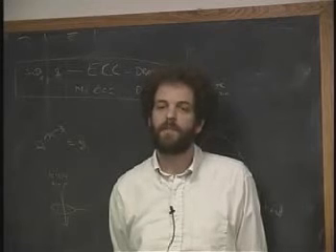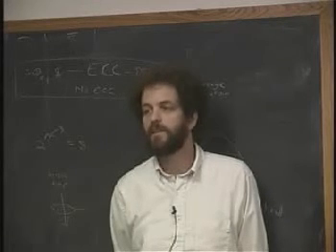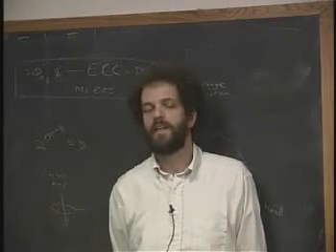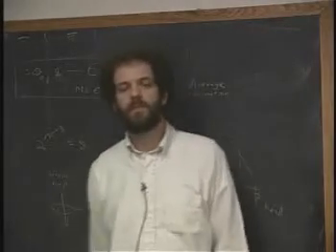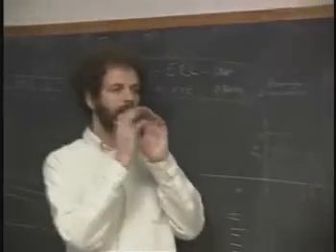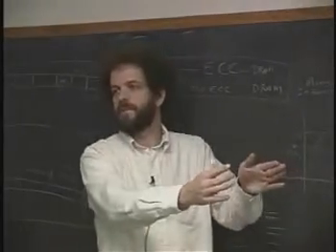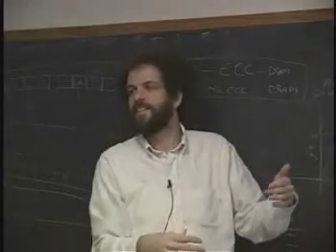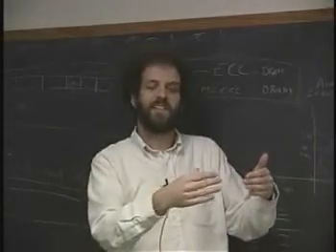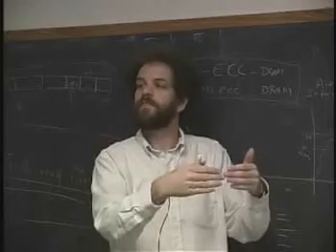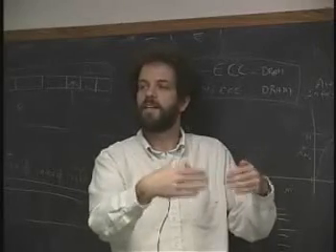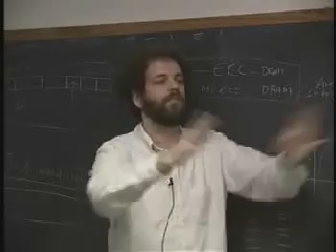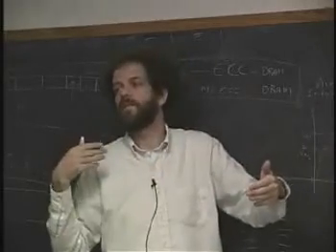The effect here is the same. If we either do not connect the wire at the end, or if we connect it to ground, we get a reflection. Okay? And it's hard to believe this, but if you're in a canyon, and you yell down the long way of the canyon, and at the end the canyon opens up into nothing, and let's say there's a ceiling to the canyon. Okay, lots of ifs here. You'll actually get an echo off of the discontinuity off the end of the canyon where the canyon opens to the wide, wide world. As suddenly this traveling wave is going pop, a negative wave will come back.